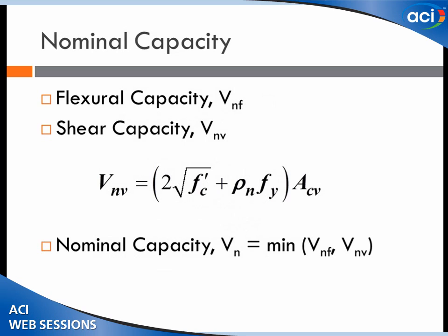A little further to some of the work related to flexure versus shear response. In this slide, which Sharon had put together, really compares a flexural strength, let's refer to that as V sub n F, F for flexure, and then there's a shear capacity or strength, V sub n V, V for shear. And the shear strength is defined by the familiar equation here.